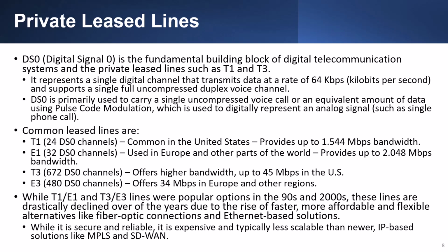Digital Signal Zero, or DS0, is the fundamental building block of digital telecommunication systems in private lease lines such as T1 and T3. It represents a single digital channel that transmits data at the rate of 64 kilobits per second and supports a single full duplex uncompressed voice channel.